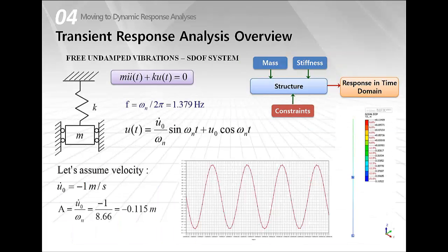Okay, now I would like to show you how to perform analysis considering free undamped vibrations. As you see on the screen, it is the same single degree of freedom system. As you remember from modal analysis, we obtain only natural frequency information. There was no time response. So as you see from the solution, we need to specify initial conditions this time for our single degree of freedom system. So let's assume the velocity in the opposite zeta direction. And let's switch once again to Midas NFX.